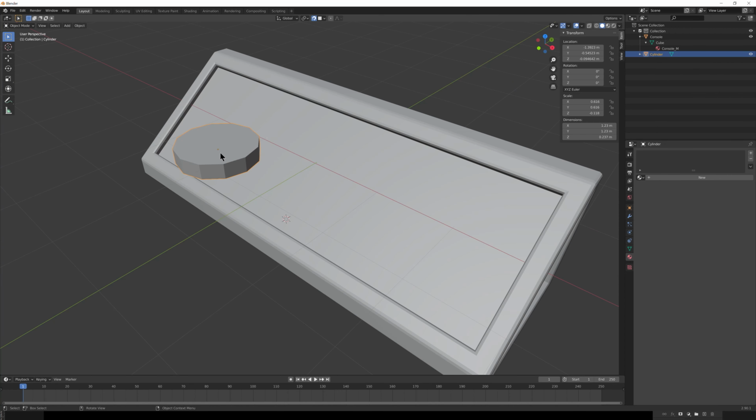Let's go ahead, select our object, and then what we want to do is use snapping to make this automatically align to our surface. So coming back up to snapping here, make sure you have face mode selected. Now, right here I have it set to closest. That is, which part is going to snap is going to be the closest one. I'm going to set that to center for right now. Also, make sure you have align rotation to target selected. I'm going to have this affect both move and, of course, rotation.